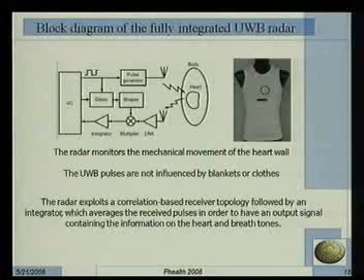The signal is amplified by a low noise amplifier, and then a cross-correlation strategy is used. So the output of the low noise amplifier is multiplied by the same pulse transmitted but delayed and shaped. And here we have the maximum of the correlation when the shape of the pulse transmitted and the pulse captured is the same. An important parameter is the delay.